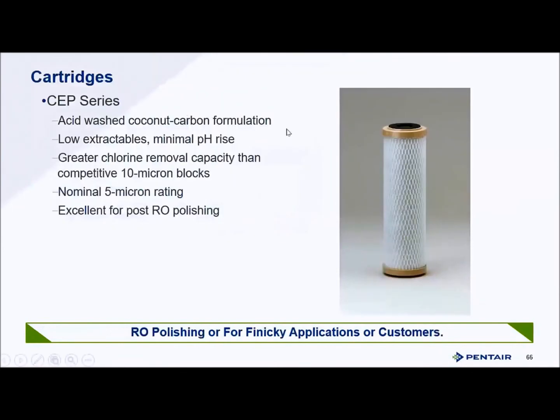CEP, this is acid wash coconut carbon for low extractables and minimal pH rise. Think about water sensitive, change sensitive sort of applications like hydroponics or dental offices. Excellent for post-RO polishing after the fact, depending on the application or the customer's concern.